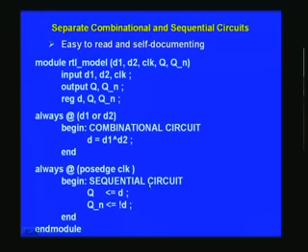So, coming back to this, we have not said what a register is. You notice that the outputs in this always block are d, q and q_n. These are all registered values. That means it is basically a flip flop here. It is not really a flip flop in the usual sense of a sequential circuit, but still it memorizes that event, because whenever there is a change only then we take action.